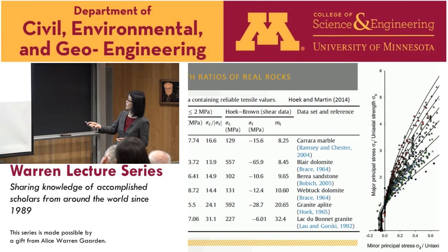With the constraint of rotation, your compressive strength goes up significantly. When you pull it apart in uniaxial tension, whether you constrain the rotation or not, the number remains more or less the same. As a result, your uniaxial compressive strength over tensile strength could increase significantly.